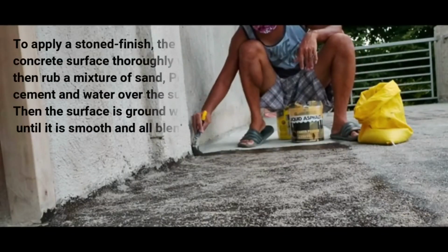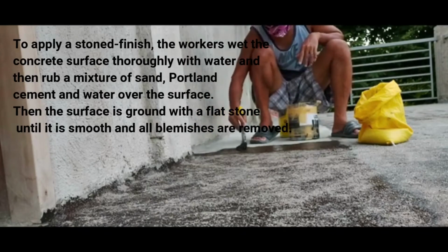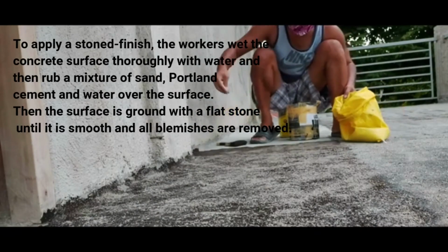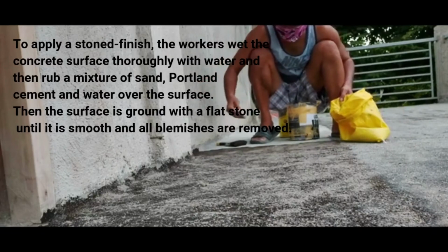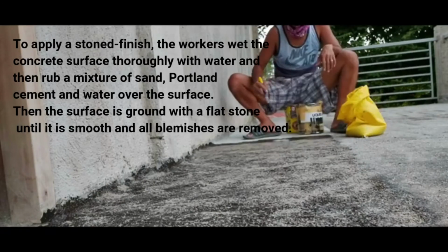To apply a stone finish, the workers wet the concrete surface thoroughly with water and then rub a mixture of sand, Portland cement and water over the surface. Then the surface is ground with a flat stone until it is smooth and all blemishes are removed.